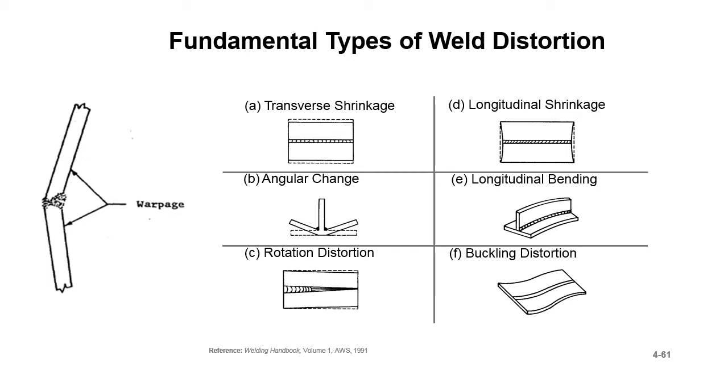And then you've got buckling distortion. This is one I dealt with in one of my previous lives. We did some thermal pre-tensioning. We'd heat up the part a couple hundred degrees right before we welded it, and then we'd weld it, and then the part would shrink back to its size that it was originally supposed to be, the size we were looking at.